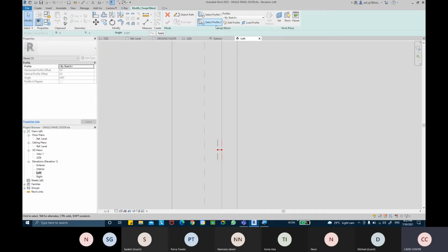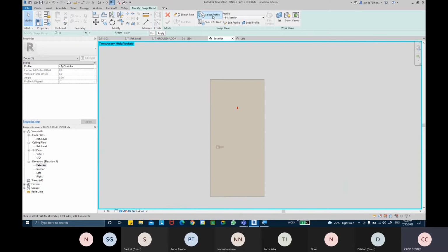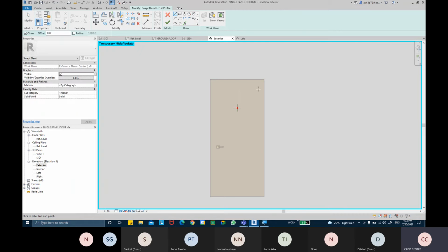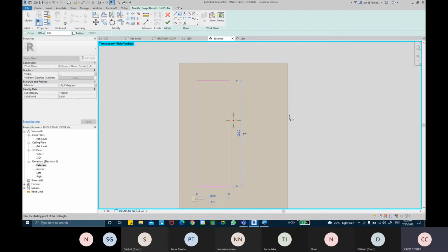And we have two profiles that we need to create. Okay, so we can come into profile 1 and profile 2. Okay, so I can come into the external part, take profile 1, edit profile, and create that shape of profile right over here. So roughly I'm just picking a shape of profile, maybe a rectangle profile, right, till here. Okay, this can be like 200 and 80 to 20, that's 300. And this I can take off like 9.